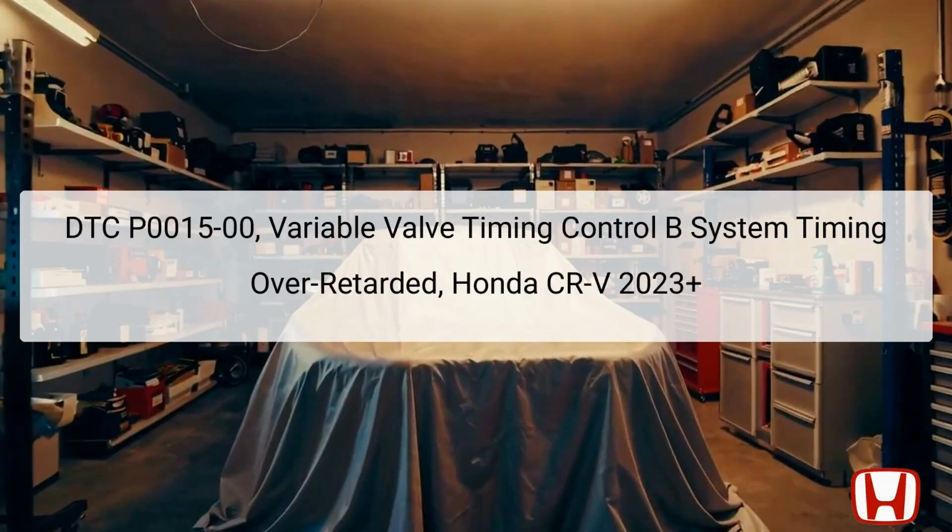This presentation aims to provide a comprehensive troubleshooting guide for the DTC P0015-00 indication, which stands for Variable Valve Timing Control, VTC, B system timing over retarded in the Honda CR-V model from 2023 onwards. When this code is triggered, it signals that the exhaust camshaft phase angle is more retarded than the value dictated by the Powertrain Control Module, PCM. The defect can degrade engine performance, fuel efficiency, and emissions.